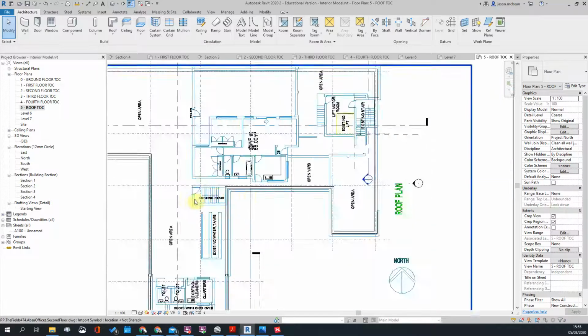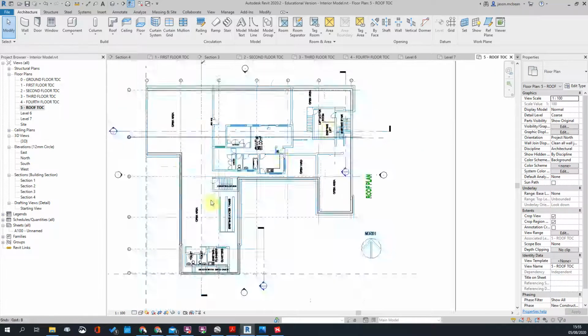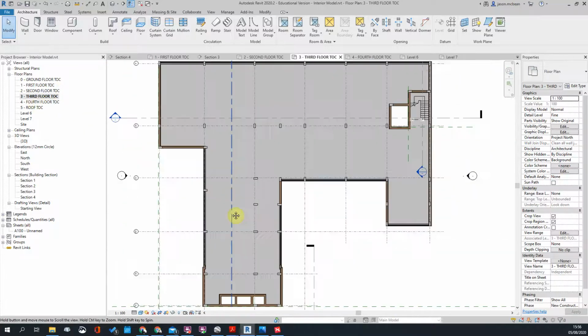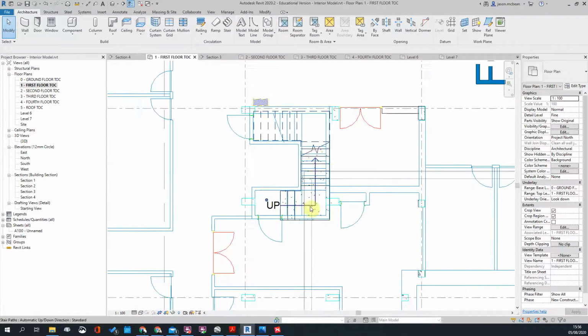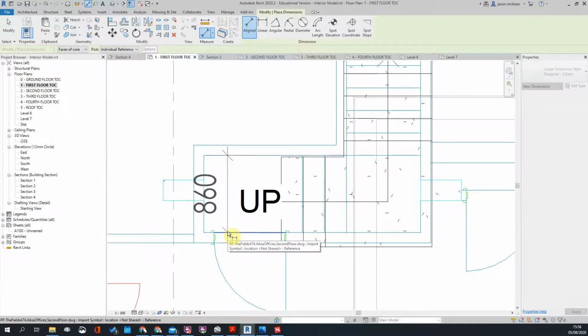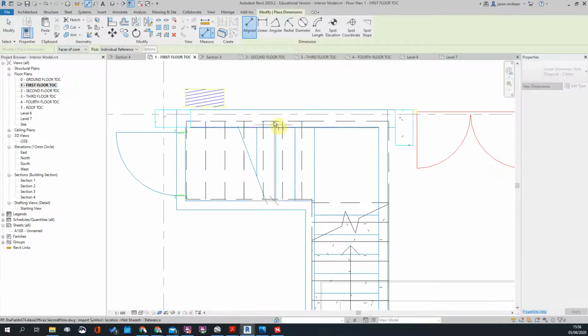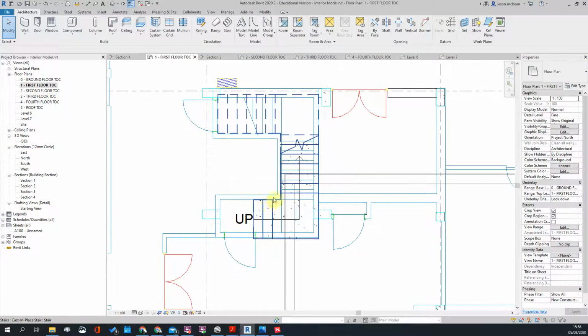Okay, and then these stairs will be the same. They will try and run the same. So the pattern of the stair technically should be the same for these stairs over here. Okay, so for the rest of the floors, let's see what the width of these stairs is, because this could be totally... wow. I'm sorry to say, but they don't do stairs that narrow. That's totally impossible. I don't know who's drawn this, but it's not great.